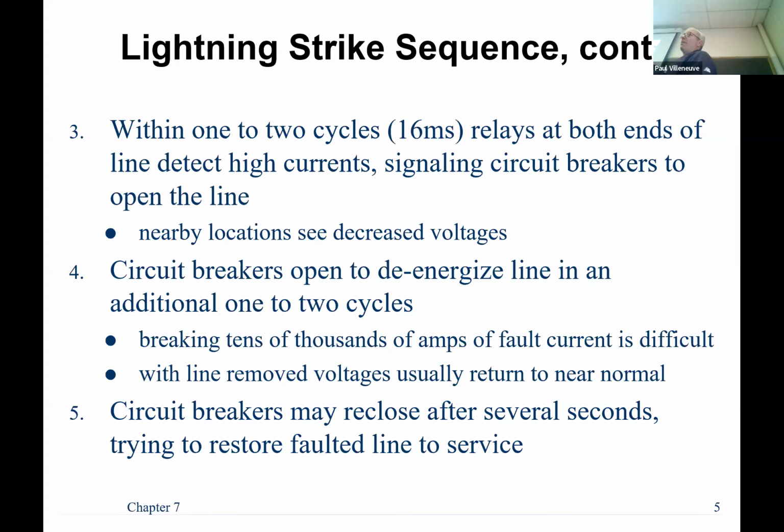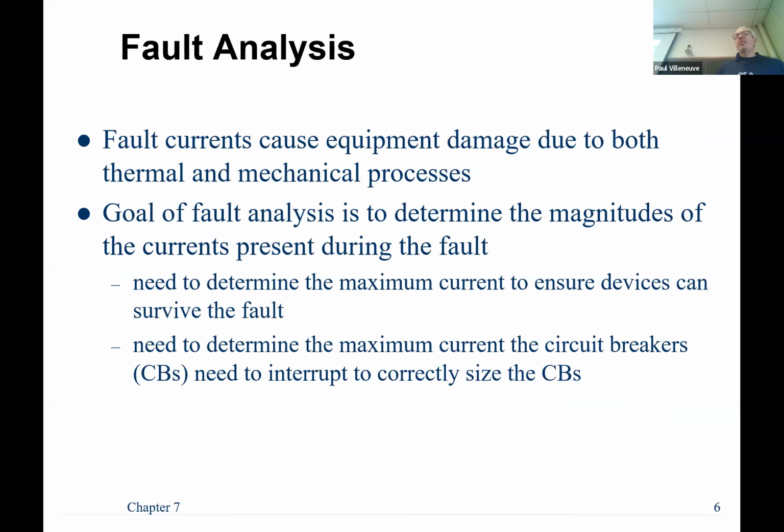That's why they warn you, right? If you're in a car and you see a wire that's down, stay away from it, because you think it's de-energized because you looked up before and there was an arc and all this stuff and now it's gone. But that doesn't mean in 5 seconds or even less, they won't do a reclose shot and attempt to do that. So that's why you got to use extreme caution because of auto restoration systems. Okay, that's what it is. So auto restoration is a good thing. That means our systems become more reliable.